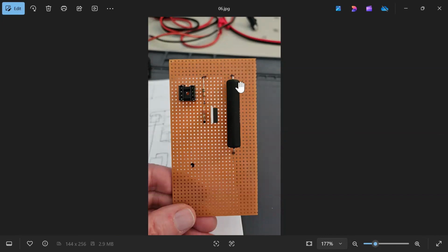So you see our power resistor is pretty large here. This is a 10 watt. We probably could have reduced this quite a bit, especially since the power is in the high power state only for 200 milliseconds. But that's what I was able to purchase. Here's the MOSFET. Here is the 10K pull-up resistor to the MOSFET. Here's the 220 ohm resistor that's limiting the current to the PIC, and here's where our PIC will go.